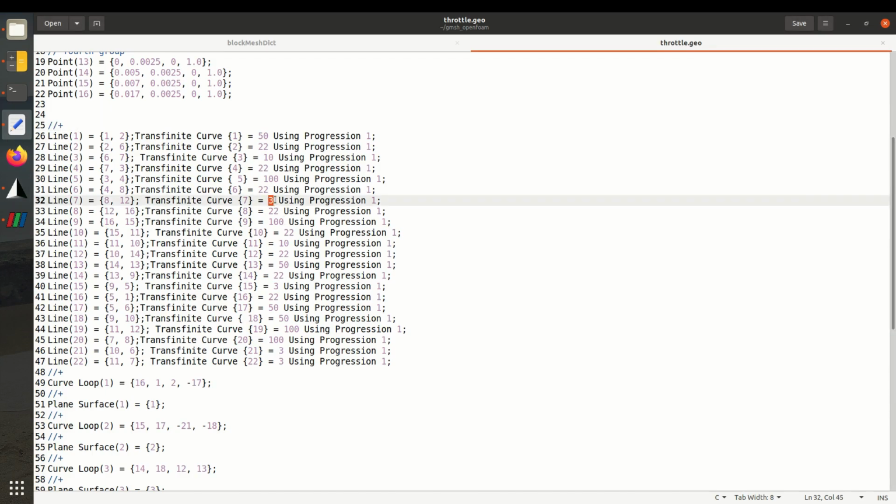So just take it as a rule in GMSH: if you want 4 divisions, choose 5 in order to get what you want. I don't know what's going on inside or how it is programmed, but if you need, for example, 3 divisions, choose 4, and so on.